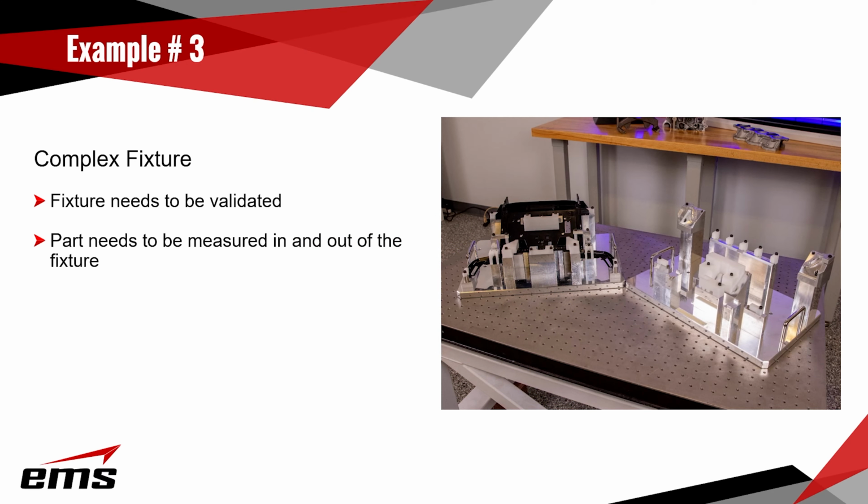and also in the fixture and look at the differences, because it can be a real challenge with sheet metal parts and thin injection molded parts to hold the correct shape. So when the part comes out of the mold, because of shrinkage and just other things involved in the manufacturing process, the part can actually not be in the correct position. Now, a little bit of that is okay, but if you get too much where you have to really flex or bend or change the part to get it to even fit in the fixture and go back to part position, there can be some issues there.